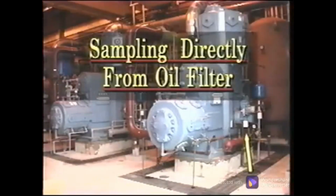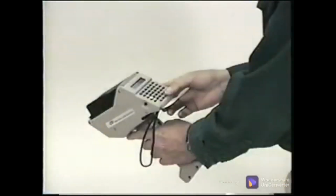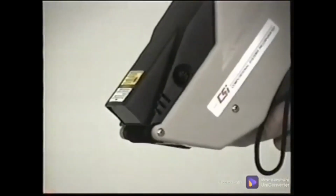As a general practice, you would not want to initiate a maintenance action on the basis of an oil sample taken directly from a used oil filter. However, this is where you will find the highest concentration of solid contaminants and large wear particles. If the filter is free of metallic debris, it is unlikely that much wear has taken place since the filter was last changed.